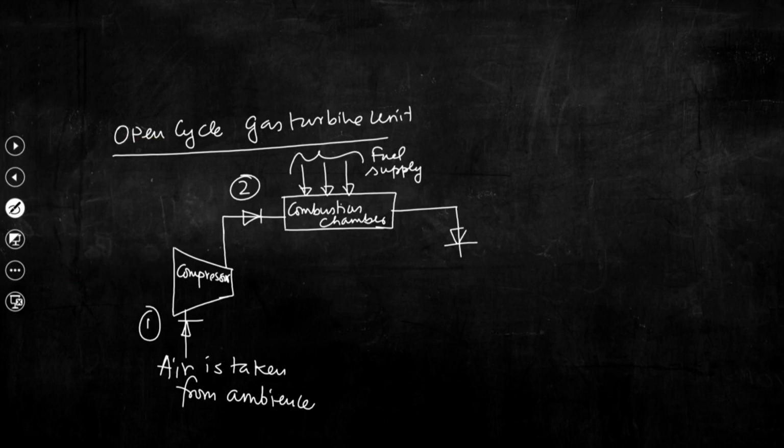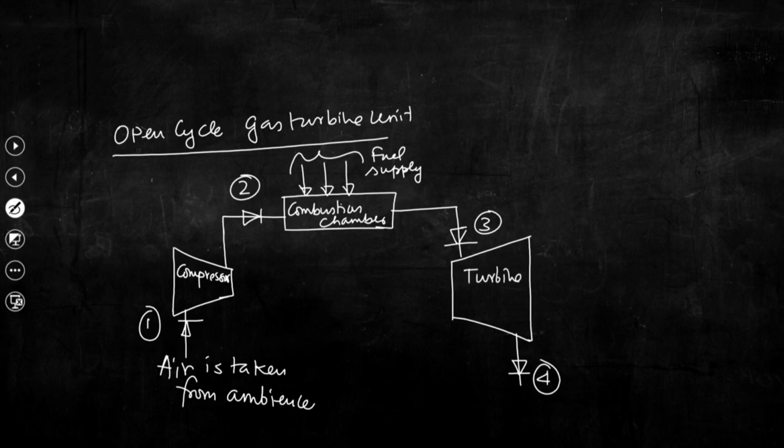into this turbine, and finally, so this is state point 3 and this is state point 4 and this is the turbine, and we will be getting work output, W. So, basically try to understand, ambient air will be taken into this compressor, air will be compressed, and at the exit of the compressor air is having high pressure, temperature is also higher than its inlet temperature of course.